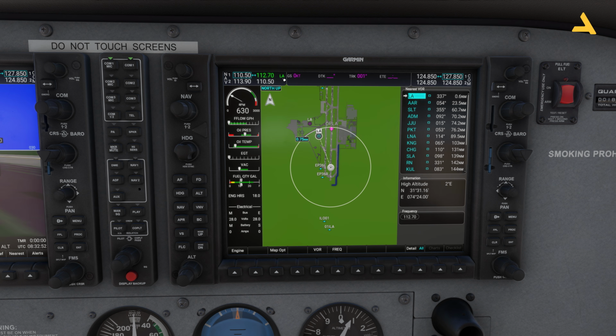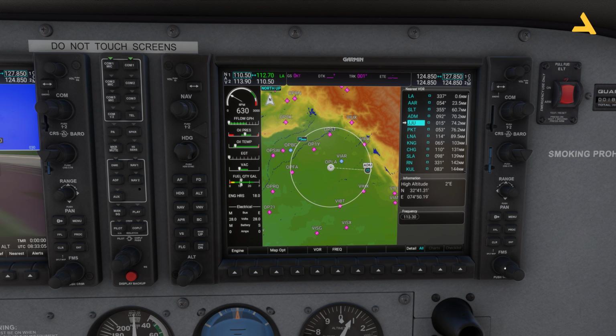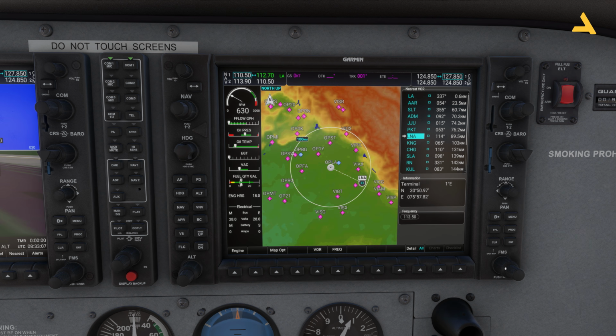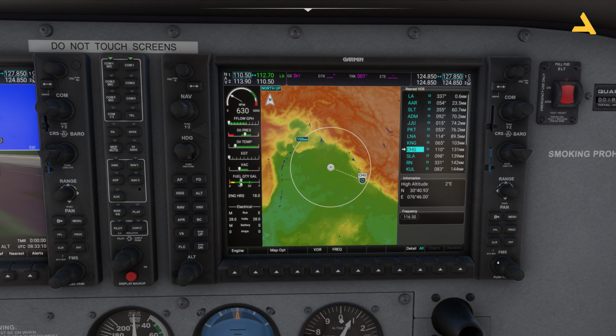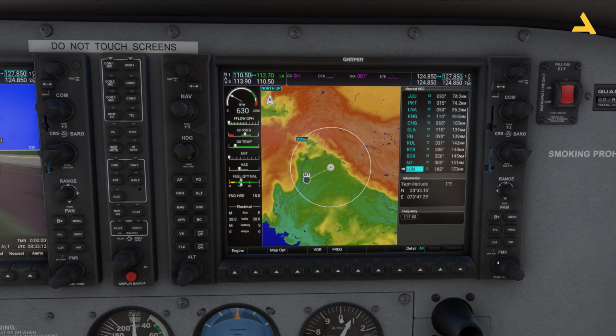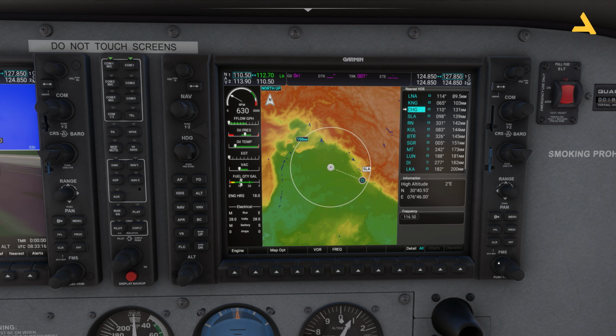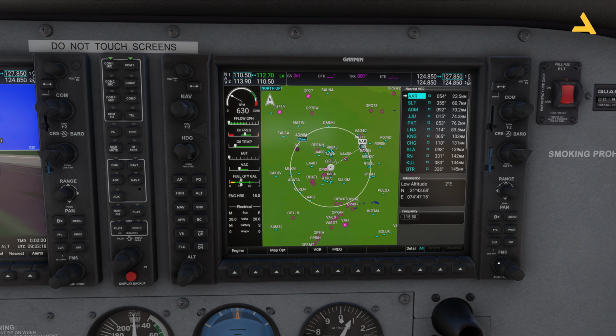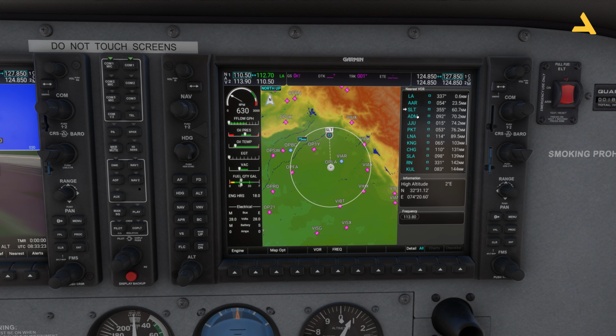And you can see LA is coming, so it means I'm tracking the right VOR, and you can see on your screen that the plane is pointing towards this VOR. Now another thing, we have to find the SLT. As I'm moving this knob, you can see all the VORs are being selected. Can I find the SLT? Yeah, here it is. It was the third one.